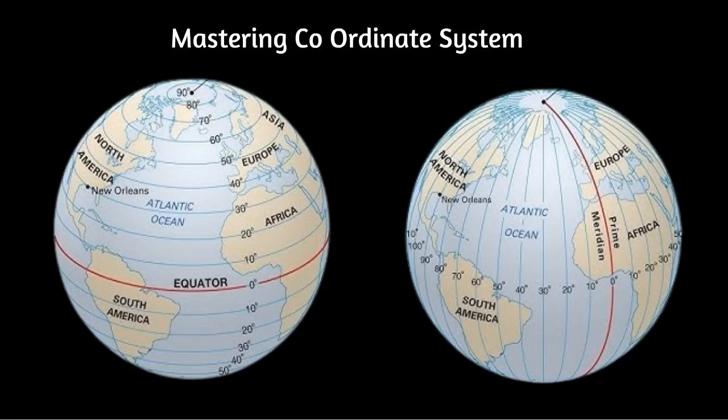Northing, that is the Y coordinate, is used to measure distance north or south from a reference point. It may be from the equator or generally from a baseline used for every project. These values are typically measured in meters and are part of the Universal Transverse Mercator or state plane coordinate system.